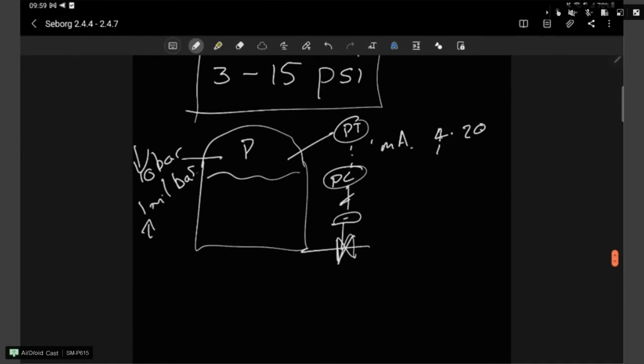We get to direct acting and reverse acting at a later stage, but in any case, let's say it acts like low value to low value. Then the pressure signal that indicates to this control valve we need to be at the lower limit will be 3 psi. That's just the pressure that is provided onto the diaphragm of this valve.